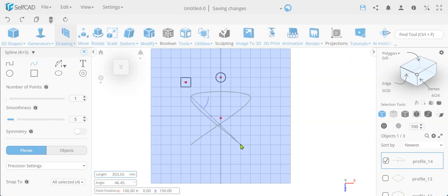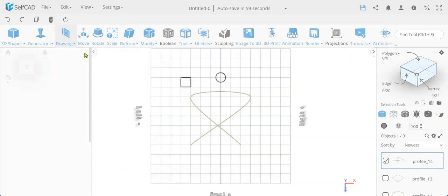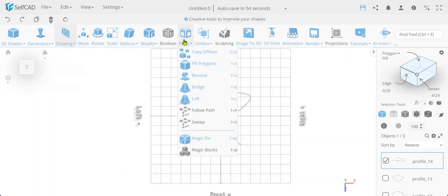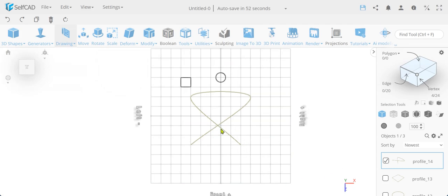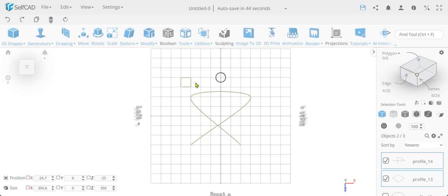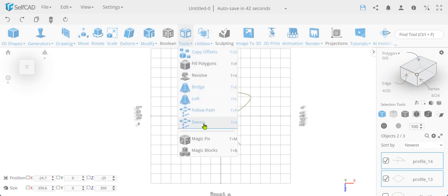If we use the Follow Path tool, or even the basic sweep mode, the resulting geometry follows the path exactly, creating overlapping faces. This produces non-manifold geometry, which can cause problems during editing or 3D printing. To demonstrate this, open the sweep tool and preview it using Exact Mode.